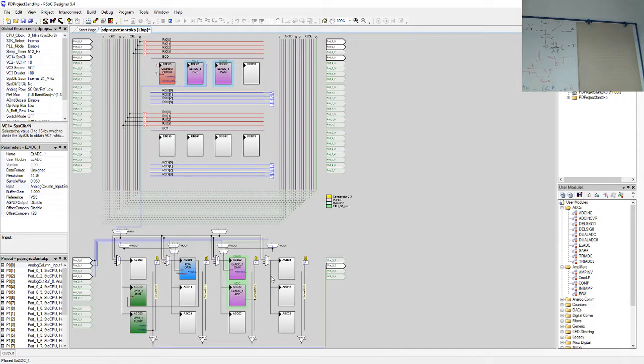So did you get all messed up? I did. So my original signal comes to port 00, and then it goes to the PGA. Then that output is going to low pass filter block here. The low pass filter block output goes to the buffer, which is connected to port 03, and then port 03 is actually connected to this multiplexer, through this multiplexer to my A to D converter. Done.